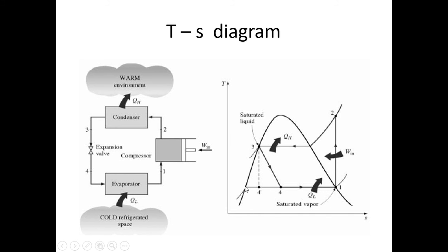So that means this much part of the refrigerant is already vaporized, and this much part of the refrigerant is in the liquid form. So then 4 1 is the evaporation. From this, 4 1 is evaporation. Again 1 is a saturation condition, and that is entering into the compressor for suction.